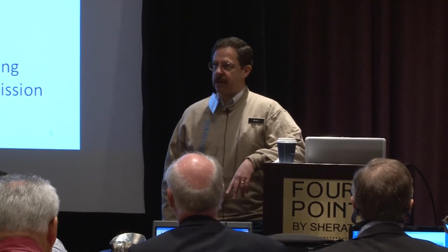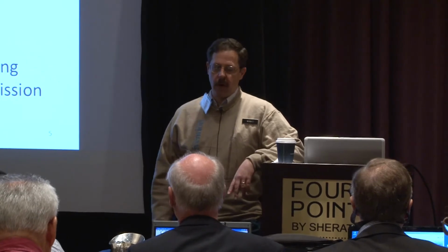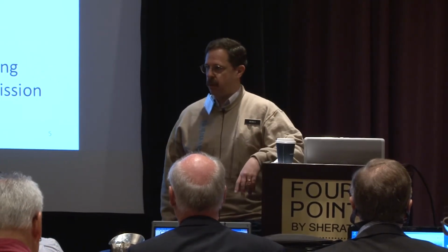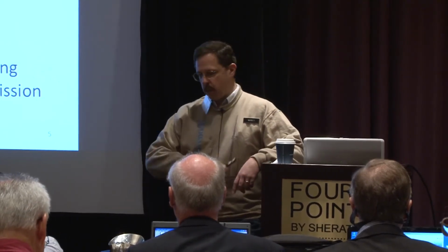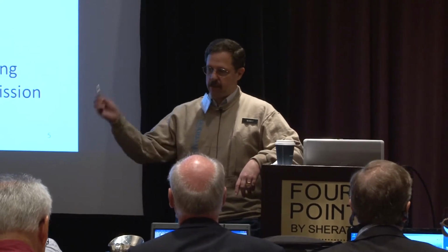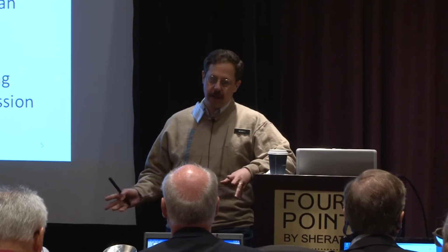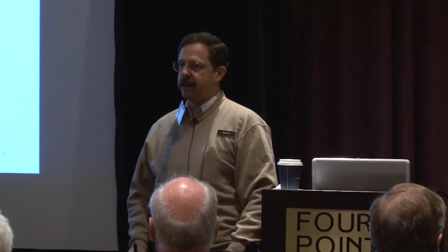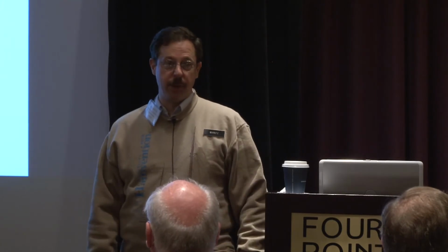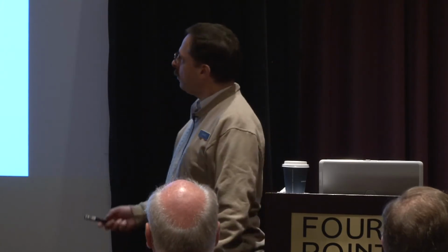So eventually a lot of hams figured out what was going on, and then you started seeing these mods showing up on the internet, and people were ripping those out and putting in semi-rigid cable or double shielded cable or whatever. And then finally, believe it or not, ICOM saw the light and actually changed their manufacturing process and put in better shielded cables, okay?